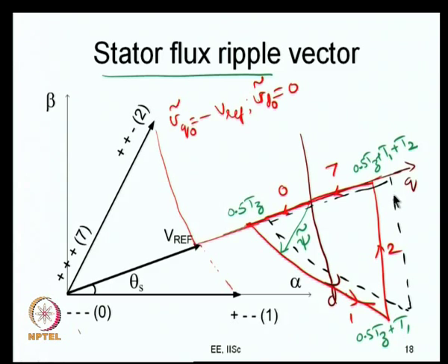When you add 1/4 third harmonic injection to sinusoidal PWM, it becomes very close to conventional space vector PWM. The division of null vector time is almost equal, and therefore you get the same thing as the red one, and that is the reason why, when you have a third harmonic injection whose amplitude is 1/4 of the fundamental,